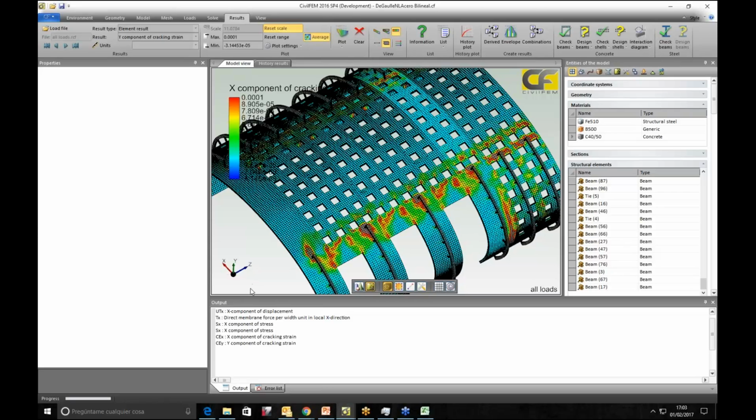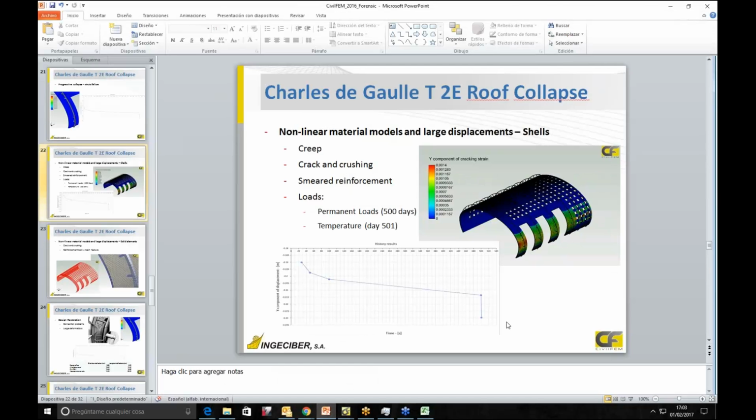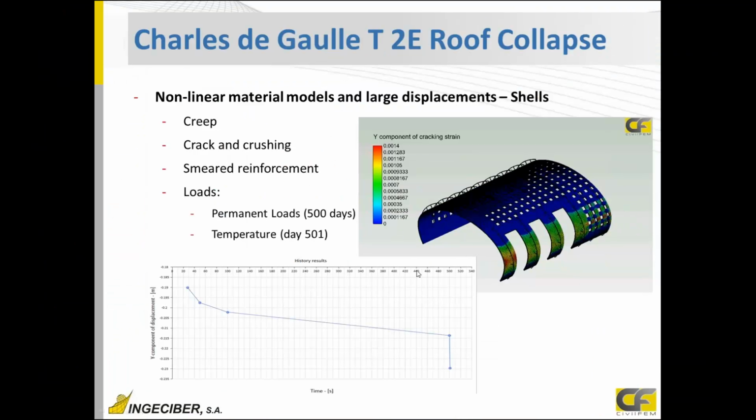Especially all the parts in connection with the steel structure, you can see that they caused cracking in the concrete layer. What we have seen is that we are getting similar values, high deformations due to permanent loads, creep and instantaneous deformations, and when adding these extra temperatures, the concrete cracks, and the connections start failing, increasing the deformed shape. This also matches the pictures from the collapsed structure, with these struts that connect the trusses with the concrete, just punching and drilling the concrete. Also, people heard cracking sounds and dust falling from the top, and high displacements were measured on the model.